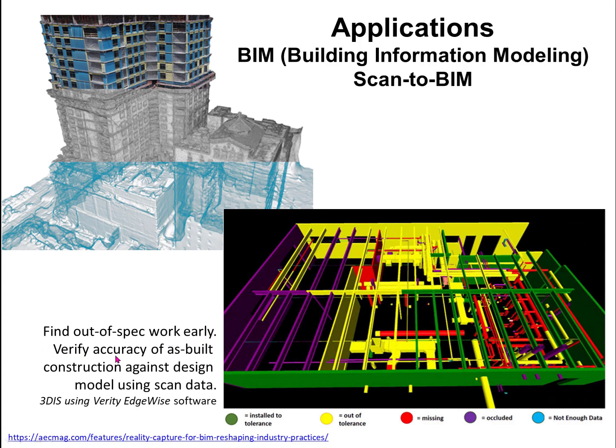So they can verify the accuracy of as-built construction against design model using the scan data. So here's an example from Verity that the green in this lower right addition, the green is installed to tolerance, green features. But the yellow features are out of tolerance and the red features are missing. So it's finding out of spec work early. It's going to be a huge industry.